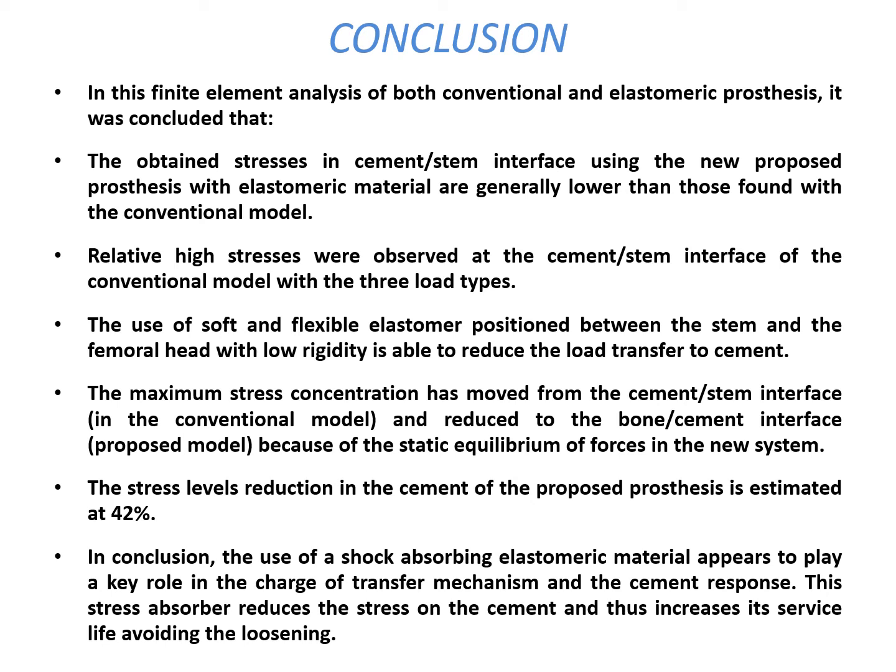The maximum stress concentration has moved from the cement-stem interface in the conventional model and is reduced to the bone-cement interface in the proposed model because of the static equilibrium of forces in the new system. The stress level reduction in the cement of the proposed prosthesis is estimated at 42%. In conclusion, the use of a shock-absorbing elastomeric material appears to play a key role in the load transfer mechanism in the cement response. This stress absorber reduces the stress on the cement and thus increases its service life, avoiding loosening.